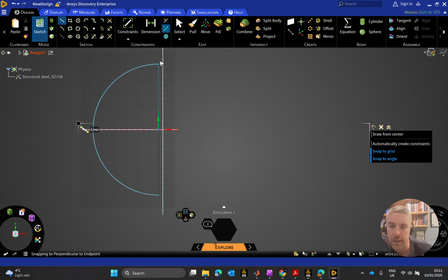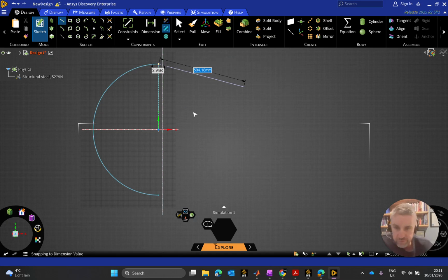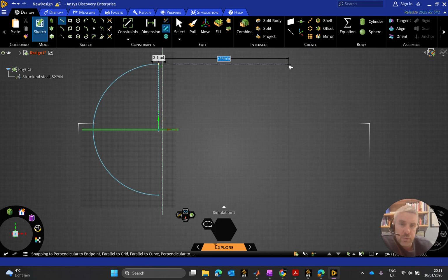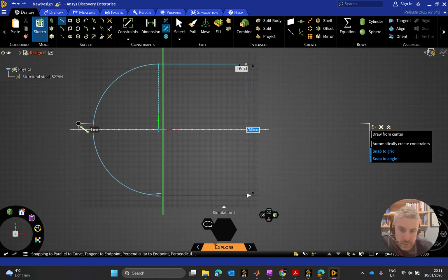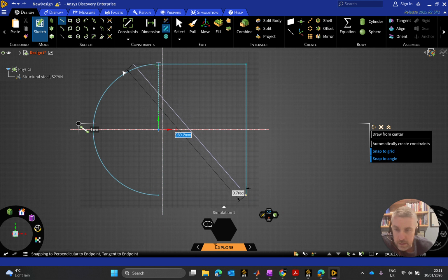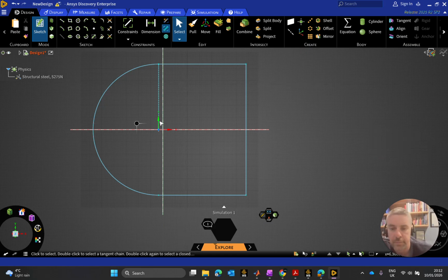Now I'm going to take a line from my top point, and I'm going to come back 20 chord lengths to the back. So 15 above, 15 out in front, 20 chord lengths to the back. My chord length in this case again is 25 millimeters. If I come 20 chord lengths back, that is 20 25s, which will bring me out to 500 millimeters. And then I'm going to come on down to here, 750 down, which is the diameter that I had my swept arc, and then I'm going to bring it here and close it up, 500 mil. All right, so there it is there.